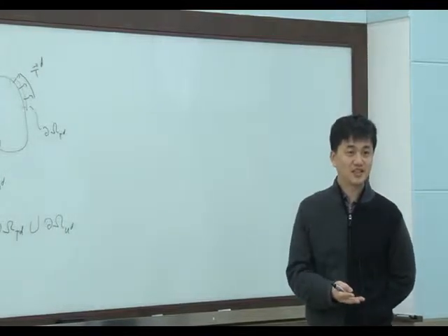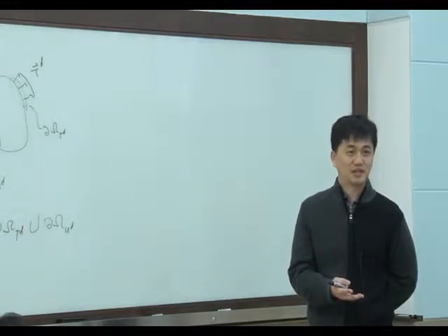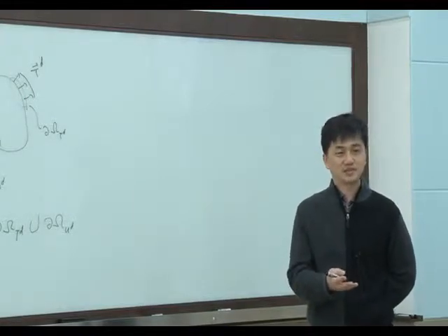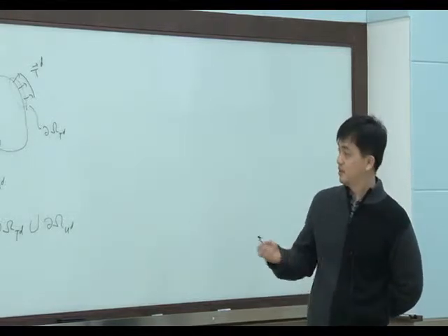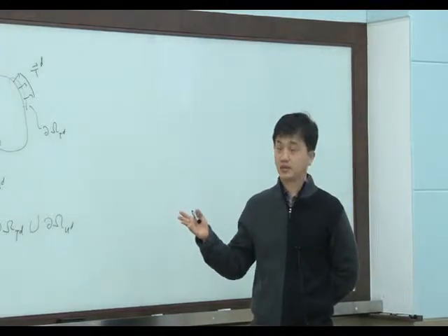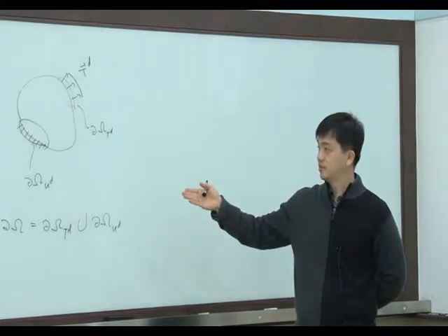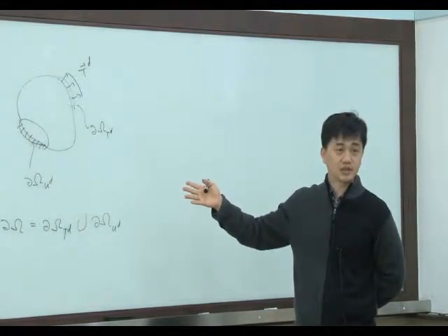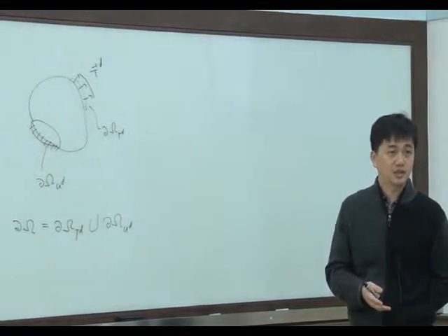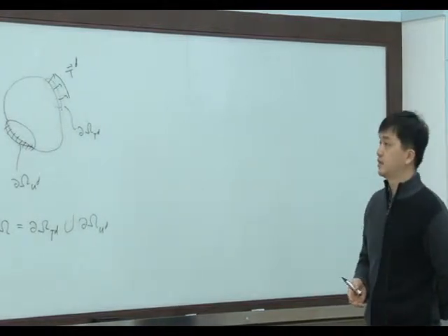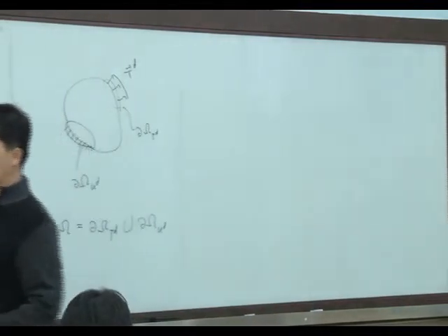But for dynamic analysis, we can have a velocity boundary or acceleration boundary. So we are saying something like an initial condition, right? Because in static analysis, the main variables are force and displacement. But in dynamic analysis, we need to consider velocity and acceleration too. I think you understand.